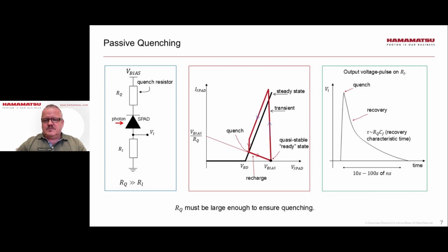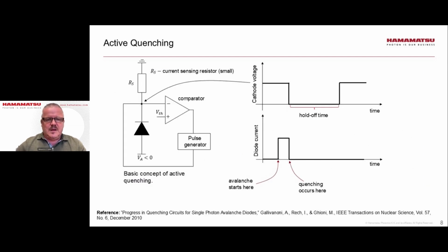During the recovery, the SPAD is still sensitive to light, though the sensitivity is greatly reduced. That sensitivity increases as the recovery nears completion. So far, we've discussed passive quenching. There are two other ways to quench a SPAD.